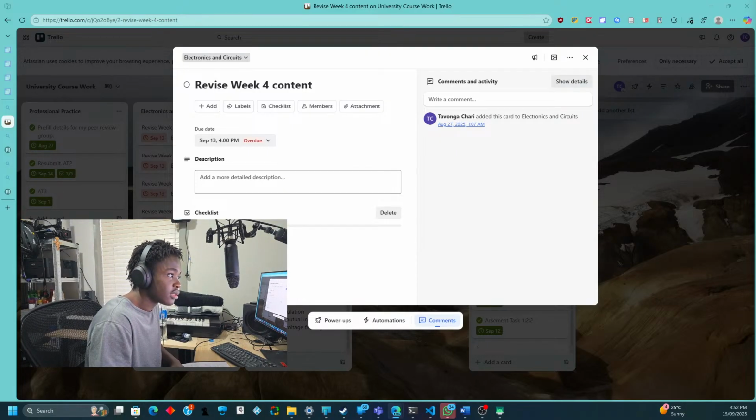So let's see, what did I get wrong? So the top right diode is pointing right. Okay, it will conduct if the left side is more positive. So it goes from 5. And then the vertical diode will conduct if the bottom is more positive.